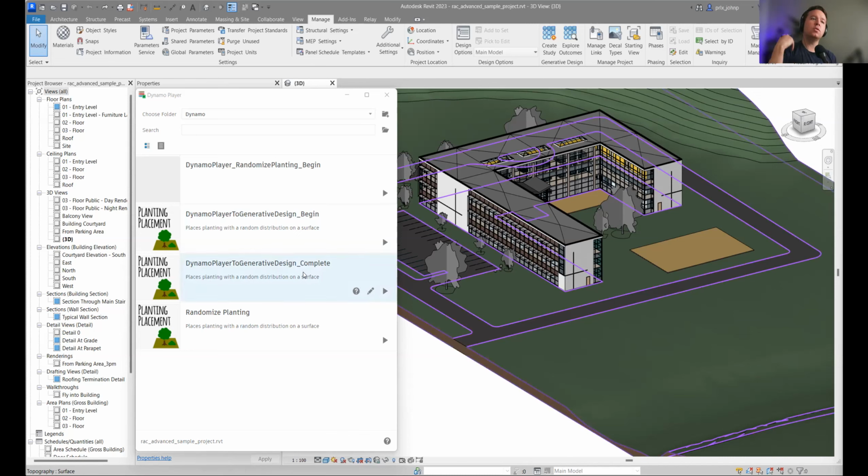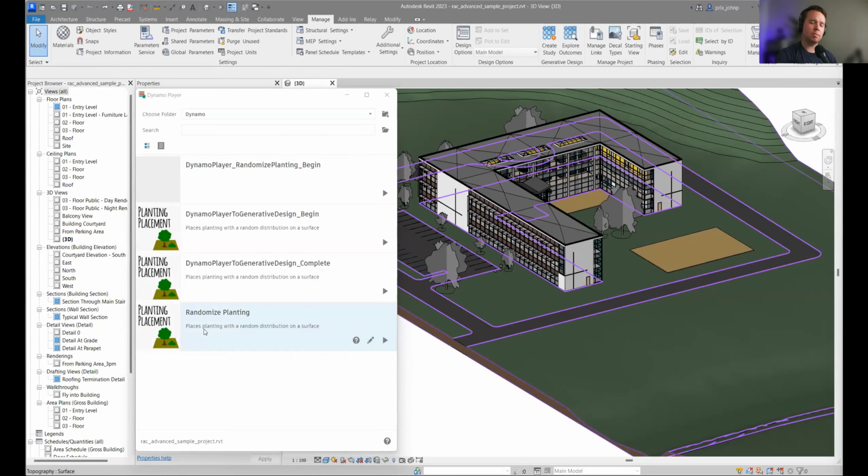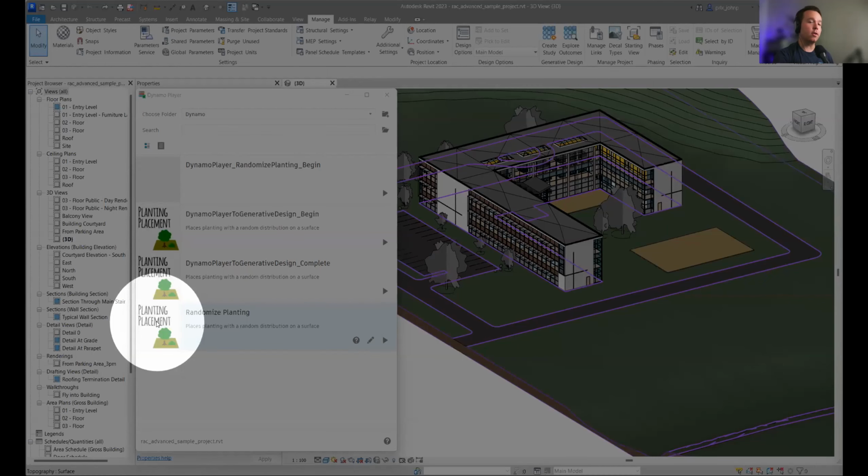Dynamo 2.12 added a lot of these features. This description on my graph was able to be added in Dynamo 2.12, but it didn't seem like it did anything. Those are under graph properties, so if you're in Revit 2022, you can start adding these right now. The image, this thumbnail, is also in Dynamo 2.12 for Revit 2022, and it serializes in your Dynamo file as base64.